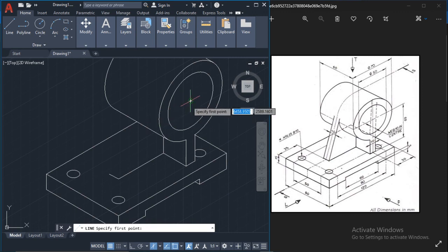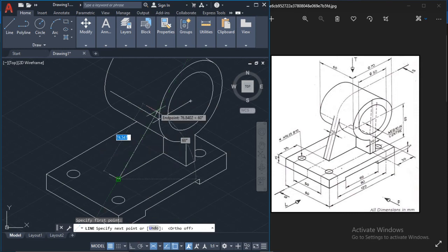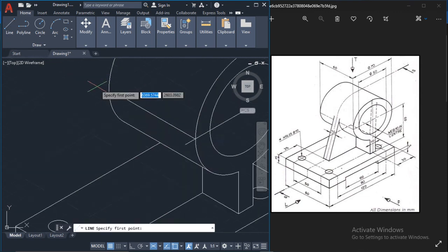It goes up to the line from the midpoint. So we can draw a line from the center, turn on ortho, because this comes up to this center here. Alright, so that means we can draw a line from here over here, and then from here we can bring this across. So let me turn on ISO top, then I can bring that across. So then I know that my lines come up to meet that line. Alright, so I can turn off ortho now, and on my slope my lines would come up to meet that point, which basically is the points that it would meet.